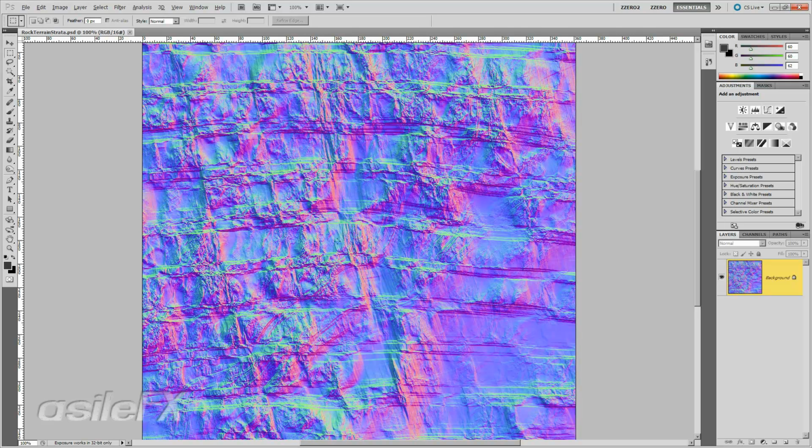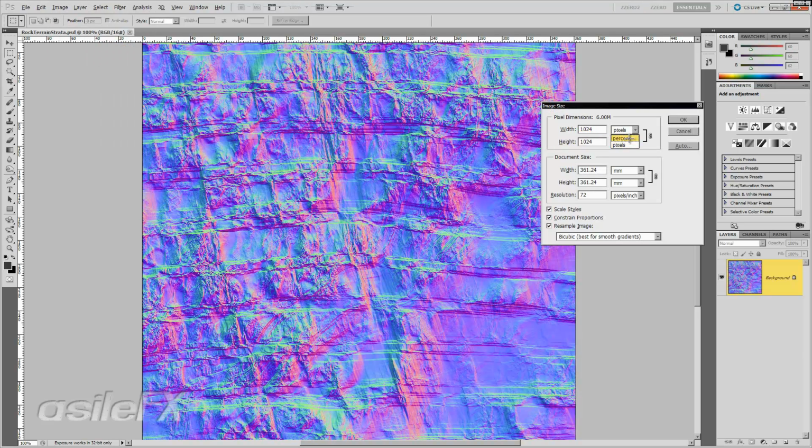If you rendered with a lower anti-aliasing, or the anti-aliasing isn't quite suitable, there's maybe a lot of pixelation within it. What you can do is reduce the image size, go to the image size, change the percent, it's about 50%, and then change the resampling mode to Bicubic.